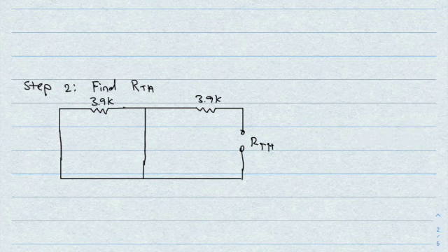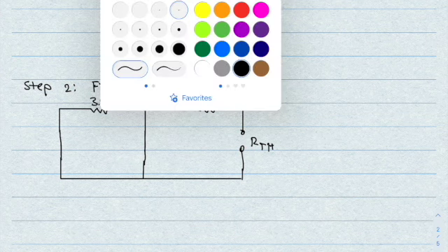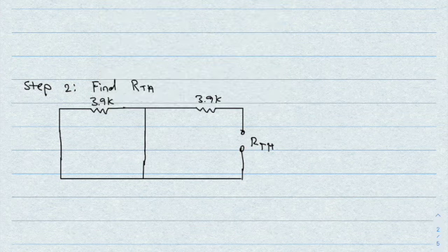This tends to be a unique situation where these 2 remaining resistors right here are neither in series nor in parallel. So what you need to do is imagine putting an ohm meter right here, right? This is A, this is B. And how an ohm meter works is it sends a current throughout the entire circuit. And we all know that current is very lazy. It chooses the path of least resistance, right? Since there's a short right here, all the current's just going to flow through there.